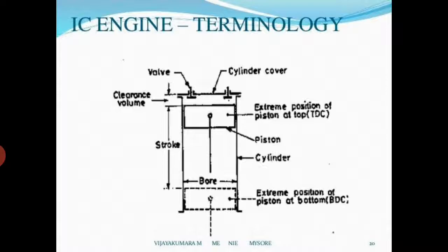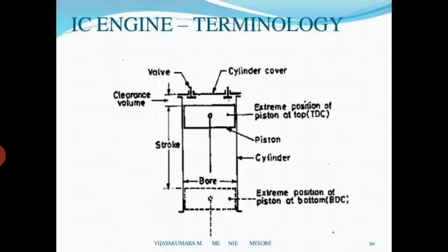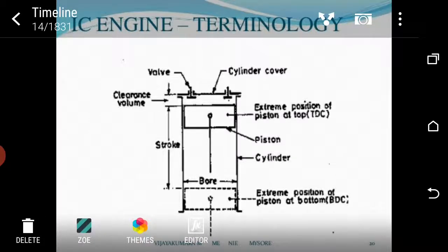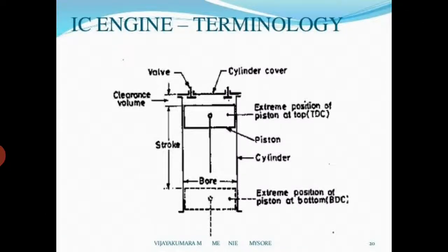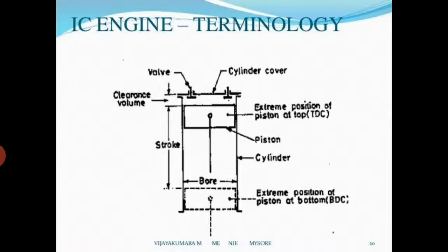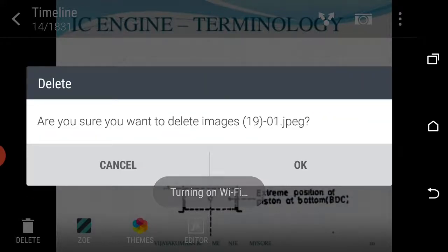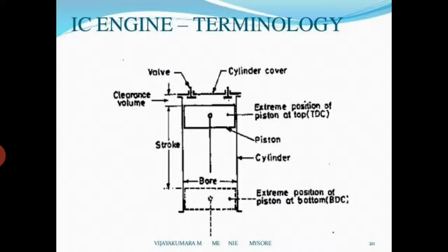Now our next topic is stroke. Stroke is the distance traveled by the piston. You can also see stroke in the slide. Stroke is the distance traveled by the piston from the extreme top position to the extreme bottom position. It is also measured in millimeter units.